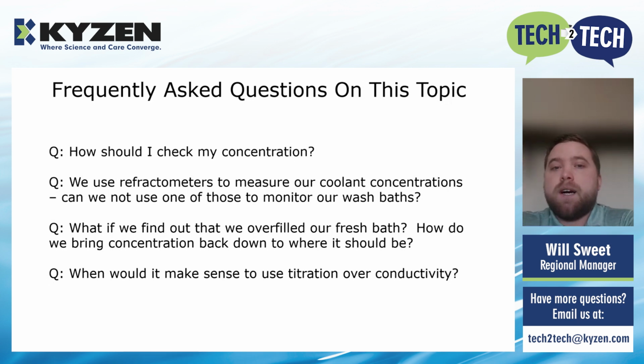But you can also do conductivity, assuming that the soils or oils that you are removing that will be in the bath are not conductive themselves. If you're able to verify that, then you can get a conductivity meter and stick the probe in a bath sample. It will give you a millisiemens reading, and that directly correlates to a % concentration.